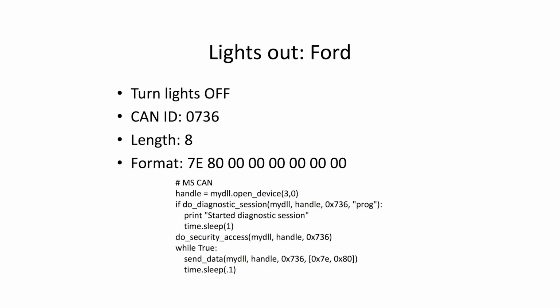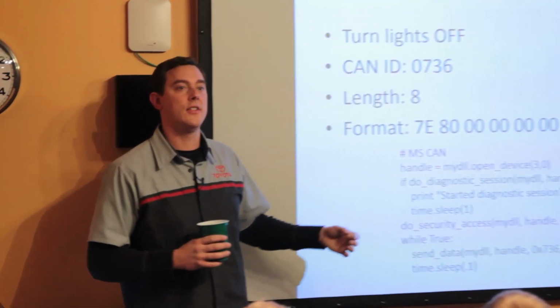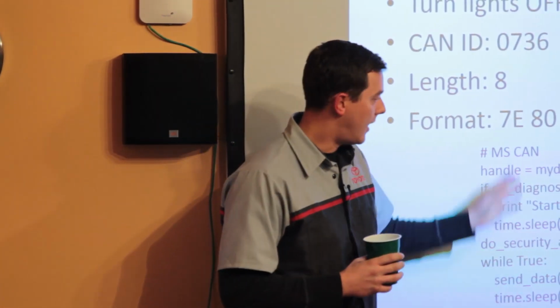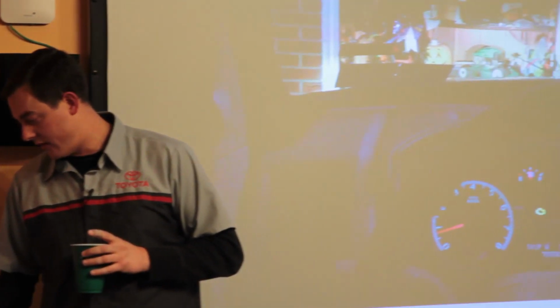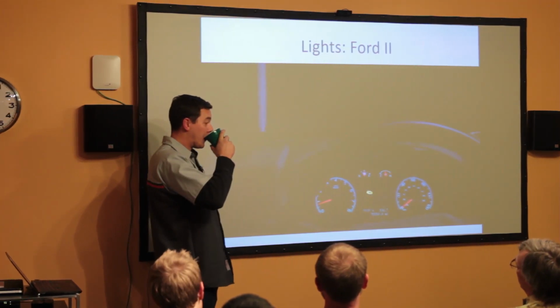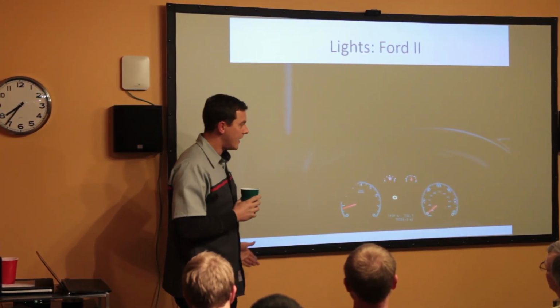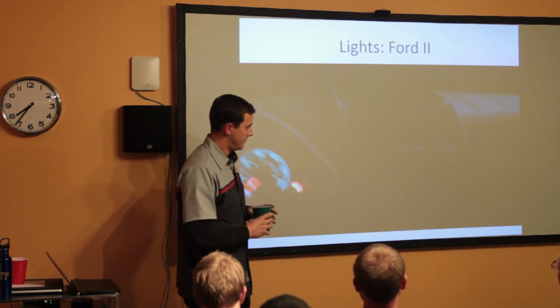The Ford did special security access, and I think it's called the Smart Junction Box. Once you put in security access to be in reprogramming mode, everything kind of shuts down in the car, which is kind of crazy. Because you need the bandwidth. So I lose my lights immediately. Yeah, they're going to want all the bandwidth for the firmware coming over. Stuff, so the radio.